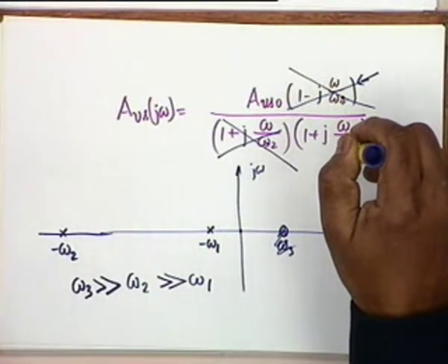C pi alone cannot do it. C pi is comparable, C pi is of the order of 10 pF, C0 could be 5 pF, one is double the other, but CT swamps everything.